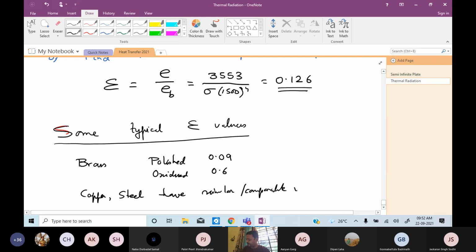Many a times, for heat sinks, the finned heat sinks, we do surface treatment. We make the surface rough, especially if you are using it for natural convection. Radiation does play a significant role. You cannot neglect it, even though in our calculations we never considered it. I won't say we never considered it. We gave you an overall value of heat transfer coefficient.